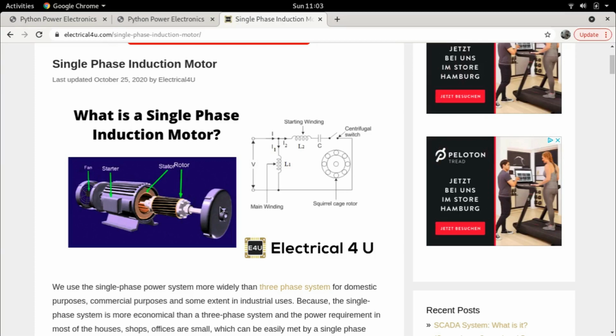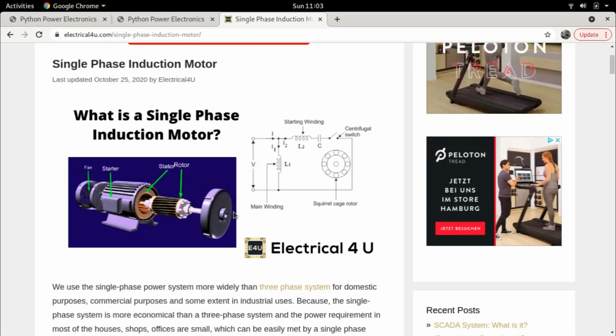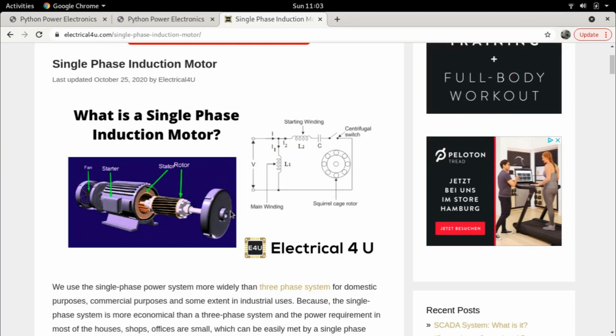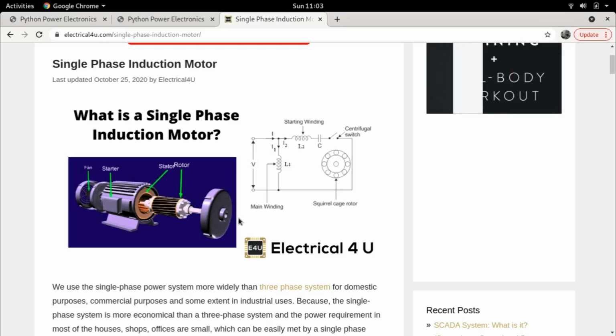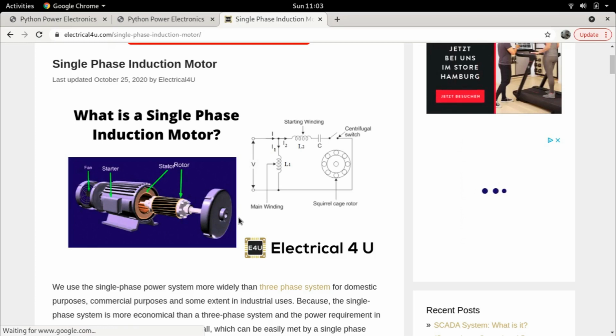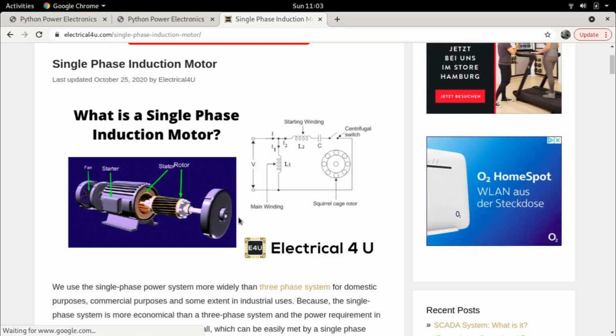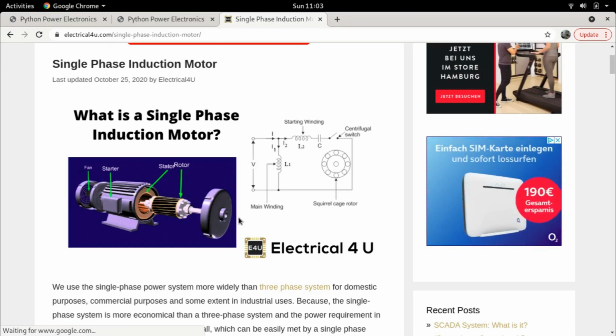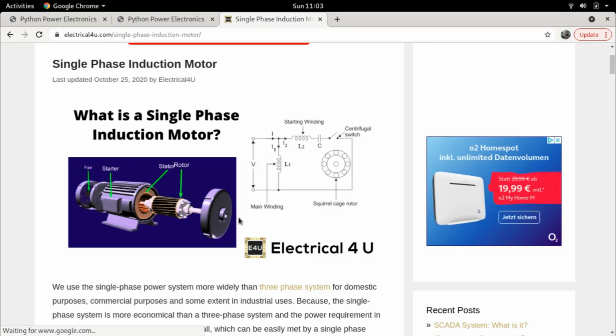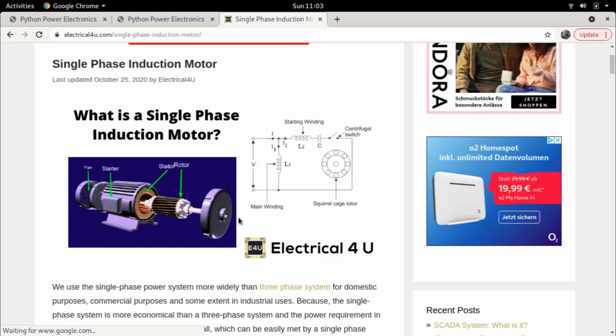Now, we need to also capture some dynamics of the mechanical system. So for example, if there is a particular load, that load is usually represented as a load torque, right? We could represent it as just a simple moment of inertia. So for example, if we know the weight of the car and the speed of the car, then this translates into a load torque. And that load torque is the mechanical load torque, which is the external input to the motor.